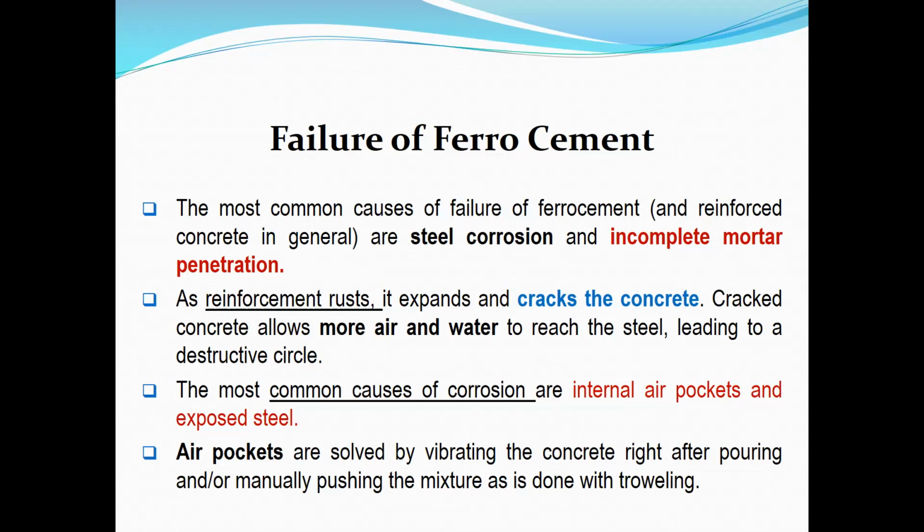shell thickness is actually less than 2 inch. So that means the concrete cover is very little. So it is very easy for the water and air from the environment to get inside. And sometimes it may not be possible to place the mortar inside that complicated wire mesh arrangement. So there remain some air pockets, and some steel may be exposed. And subsequently, due to the presence of these air pockets and exposed steel, the corrosion takes place. So corrosion is more in ferrocement than in conventional concrete.